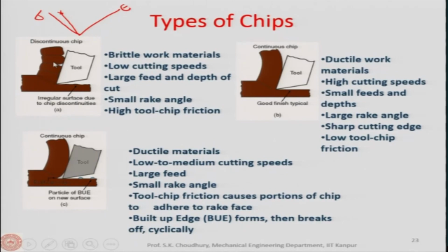Whereas, in case of discontinuous chip, since the chip is breaking, it is not in constant touch with the tool, and that much heat will not be conducted to the tool. Second thing, this you can take as an advantage of the discontinuous chip.